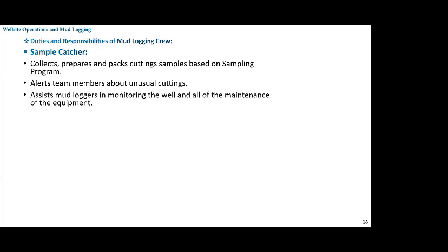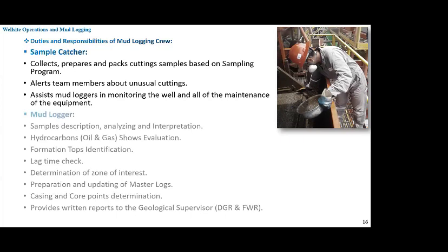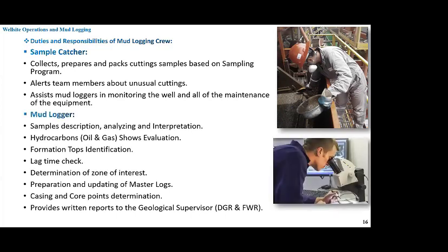The duties and responsibilities of the mud logging crew, for example, sample catcher: collects and prepares cutting samples as per the sampling program. Also assists mud loggers in monitoring the well and maintaining the equipment. This is a typical image of a sample catcher taking a cutting sample from the shale shaker. The mud logger describes samples, analyzes cuttings, and makes interpretation. Also evaluates hydrocarbon shows, oil and gas. Identifies formation tops. Also checks lag time every time, as per the program.